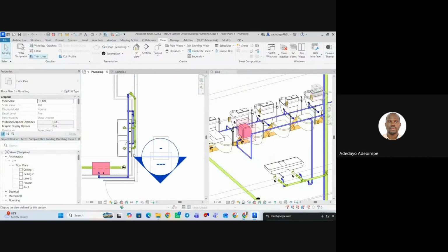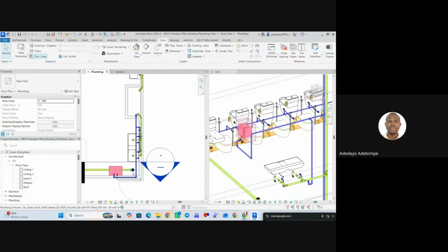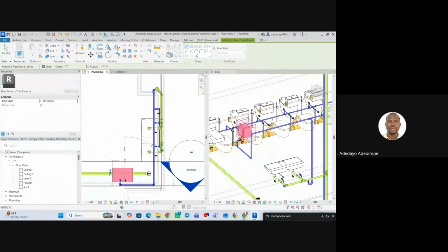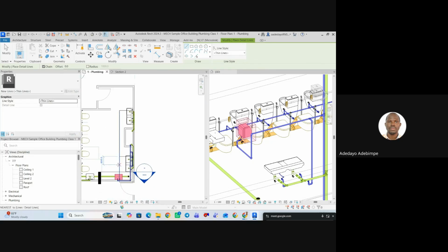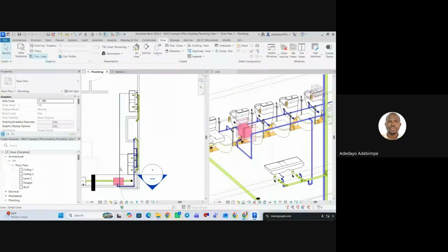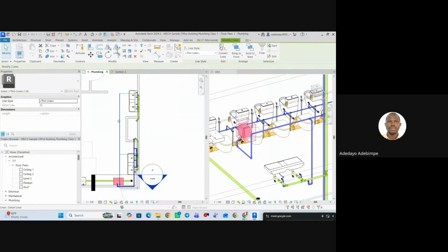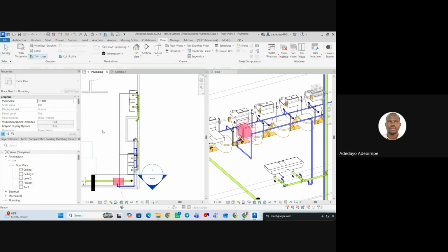Maybe. But what I'm predicting ahead of time is, yeah, I'm going to probably have clashes. So what I want to do is bring my hot water pipe, detail line, back up to a high level. Then from here, supply each point. This is the routes tab to select. So this is the route I would like to propose. Reason why is because I'm trying to avoid clashes.